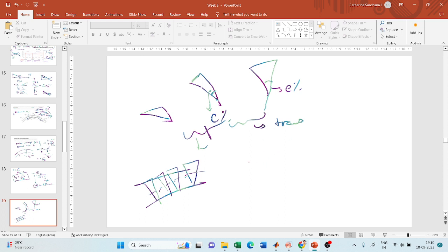Now, how will you do that? What is the equation for that? What is the rate of change of super elevation? Let us take the rate of change of super elevation as E divided by L. So this is the rate of change of super elevation along the length. With each passing distance, what is the change in super elevation? So this is nothing but, let me take it as 1 by n. This is also kind of like a slope, right? So this is taken as 1 by n is equal to E by L.